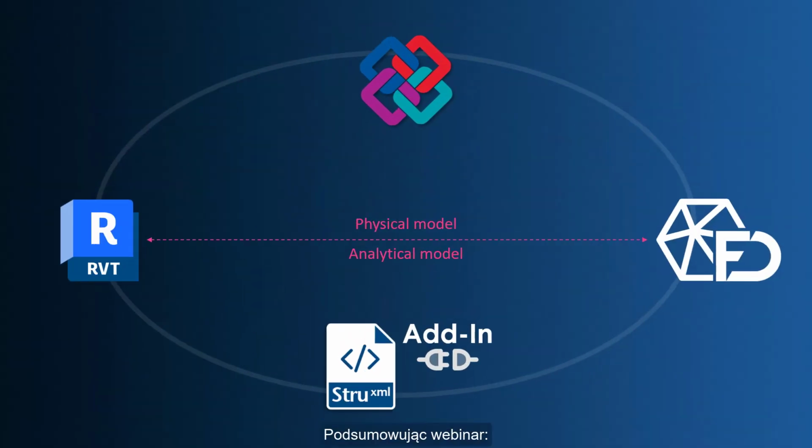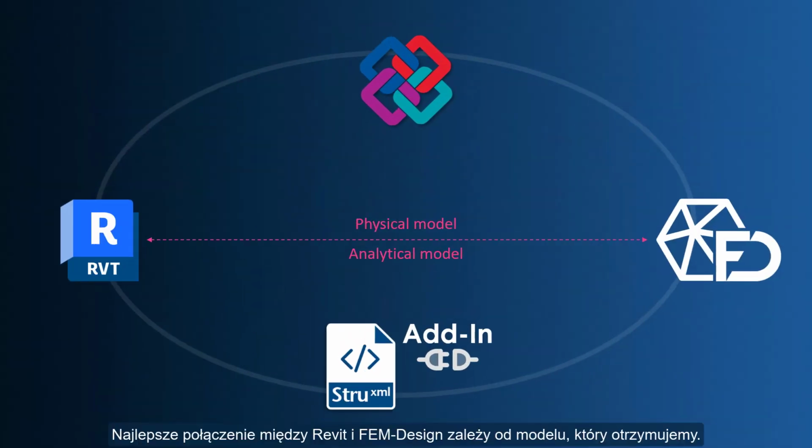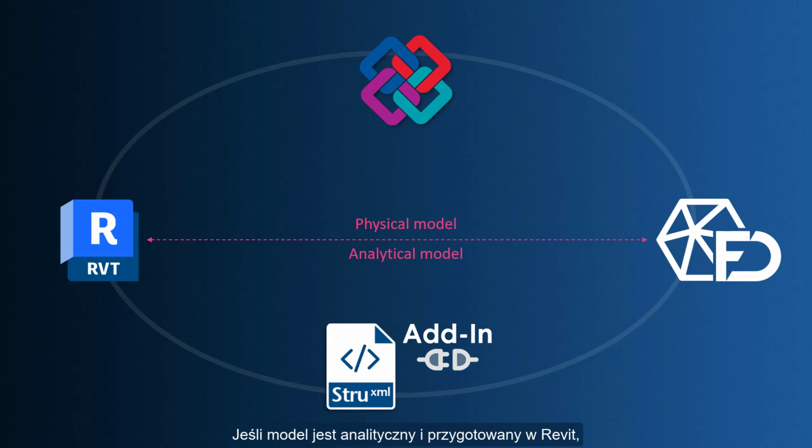To summarize the webinar, the best connection between Revit and FEM-Design depends on the model we receive. If the model is analytical and prepared in Revit, the add-in and StruXML workflow is usually the fastest and most direct option. If the model is a physical, architectural, or structural model, IFC is often the better choice.